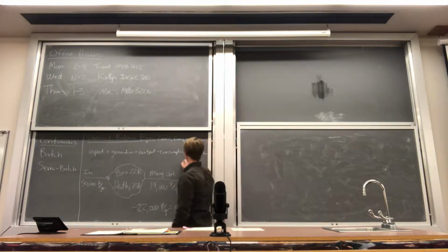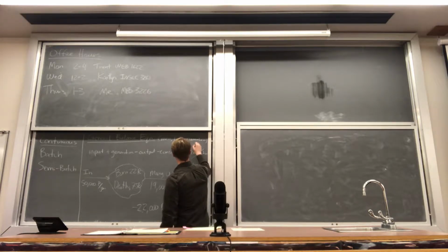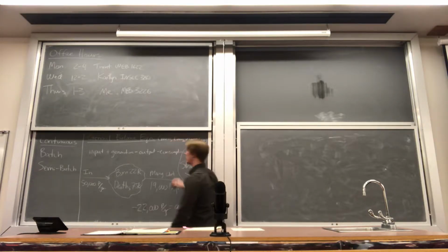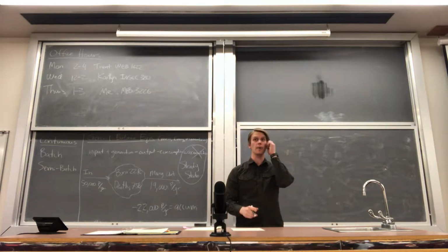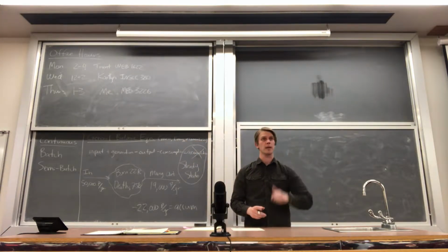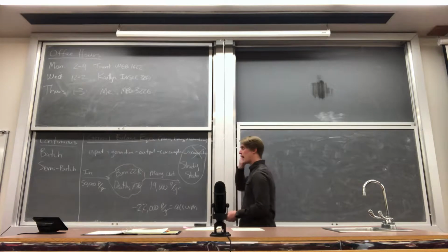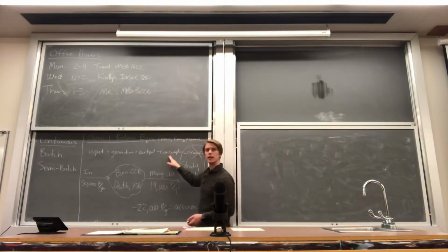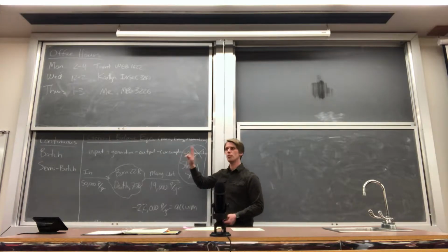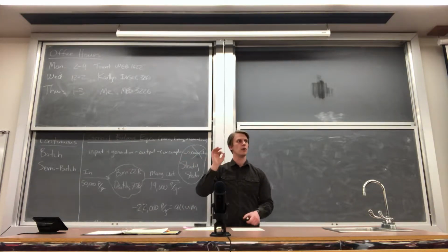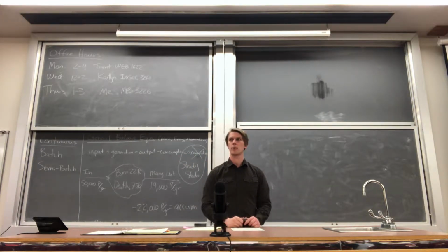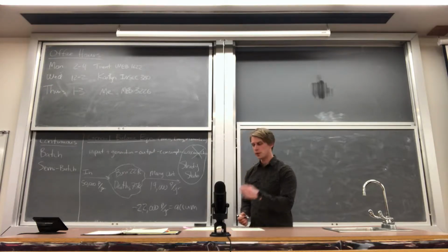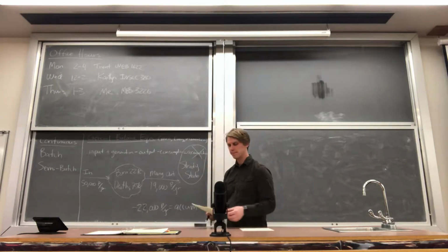This is for a steady state process. So accumulation is zero in a steady state process, and that's the most common approximation that we are going to make. For mass and energy, generation and consumption go to zero because you cannot create energy, nor can you create mass in a chemical process. You can only work with the material that comes in or comes out of the system.